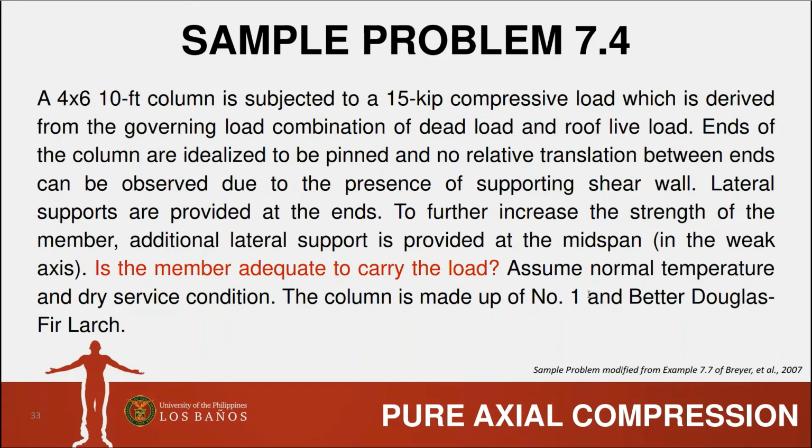Okay. So we have here sample problem 7.4. A 4 by 6, 10 feet column is subjected to a 15 kip compressive load, which is derived from the governing load combination of dead load and roof live load. Ends of the column are idealized to be pinned, and no relative translation between ends can be observed due to the presence of a supporting shear wall.